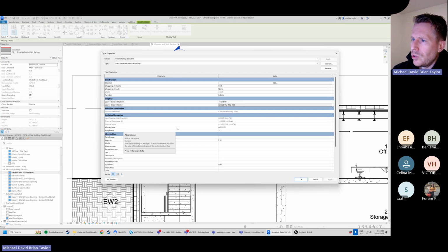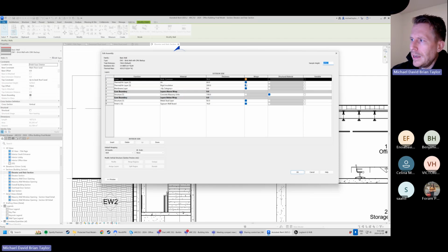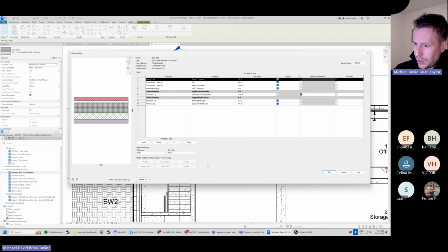But the first thing that we're going to do is we're going to jump into structure. If you remember the structure edit, and click that. And now it's a menu. But what we need to do is we actually want to see in the section view what's happening at the top of the wall. So we want to see that little wall sweep, that little cornice at the top. How do we do that? We actually, to jump over here, there's this little preview button at the bottom left of this little menu. Hit that preview button, and you'll see first step, we've got the floor plan. So if we remember, we can modify anything within our structure, the thickness, the material, the function, and that's going to update what's happening in our little section preview here.